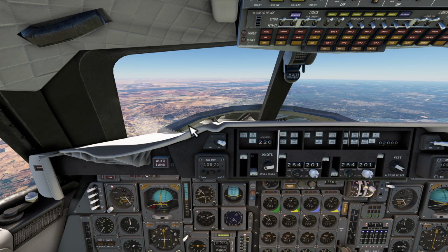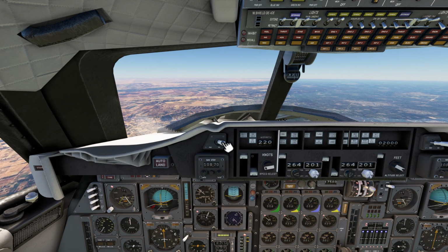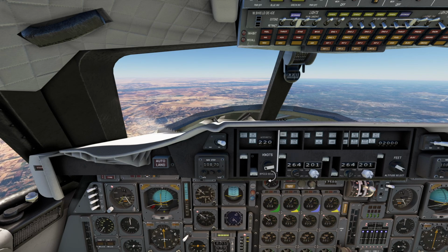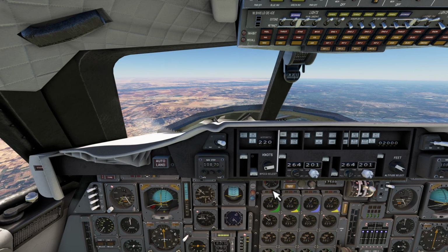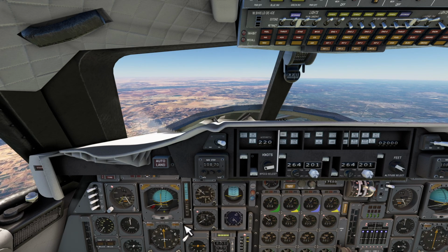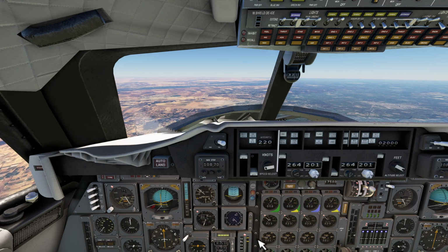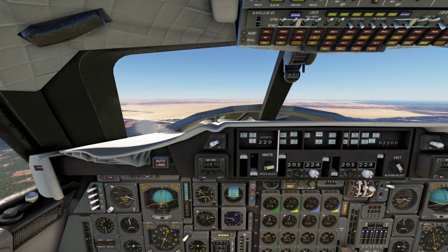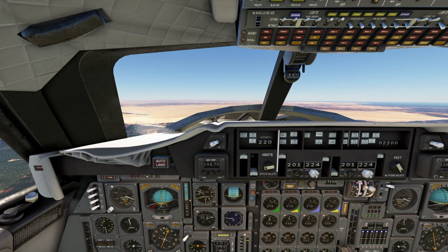And as soon as we get closer, we're gonna change to RAD, and we will have the ILS pre-programmed, so that would indicate the ILS down here with the DME, like in normal airplanes. We are approaching our final turn into the ILS of runway 23 left in Cairo.